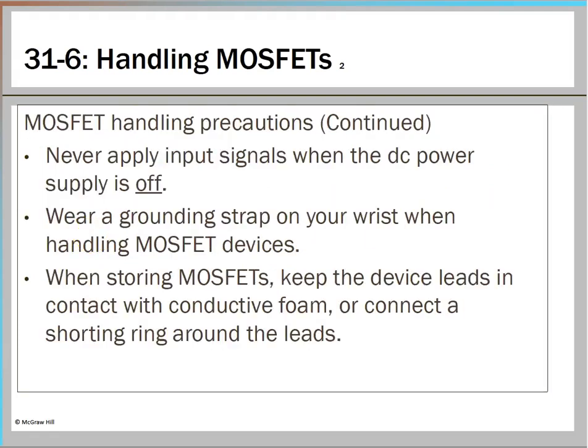Next, never apply input signals when the DC power supply is off. Always wear a grounding strap on your wrist when you are handling the MOSFET, and store the MOSFET in contact with conducting foam.